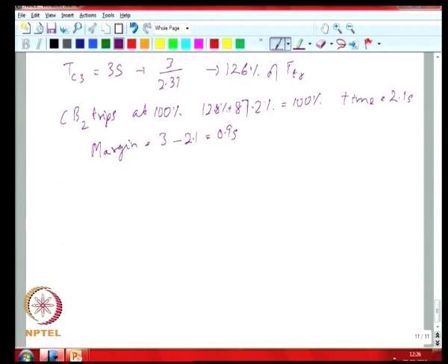So, you can see that the margin is reducing as the current level becomes lower and lower. At very low current levels your breaker needs more and more time to trip. So, at some level there is a possibility that you might actually cause a lockout before your breaker operates. You could decide on what your threshold level for your recloser needs to be.